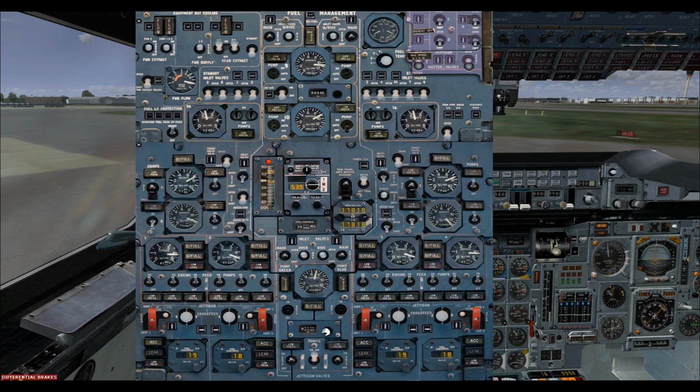below where the fuel level is now. So I'll just put it down to, say, 5,000. And then you increase your load limit controller in the top to be higher than what's already there. And you're going to move fuel back from 11 all the way back into 9 and 10. Obviously nothing's moving yet because it's not high enough. I need to be at 20,000 almost. So we're just going to zoom that up,